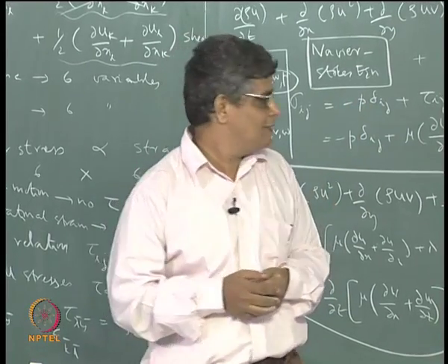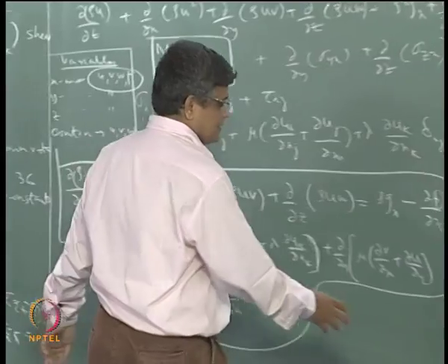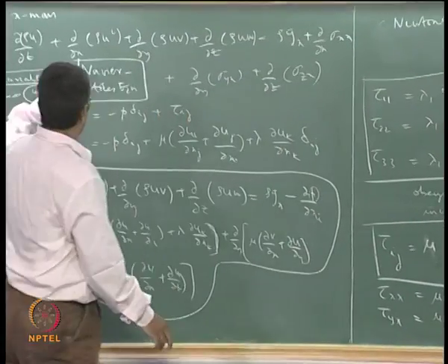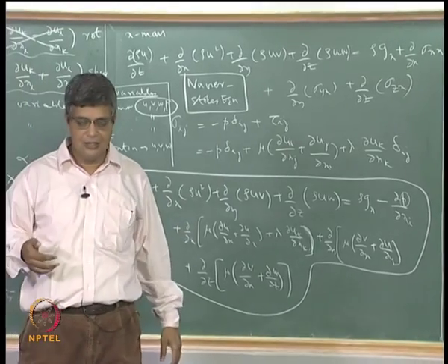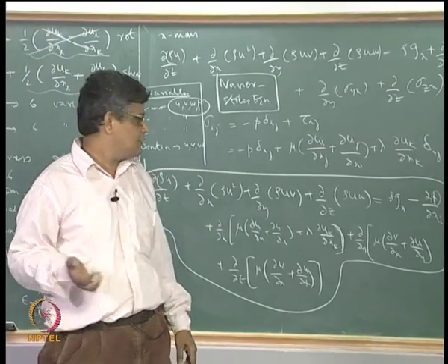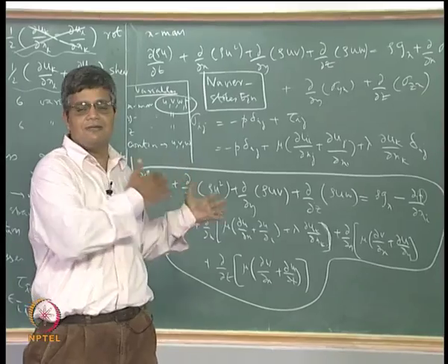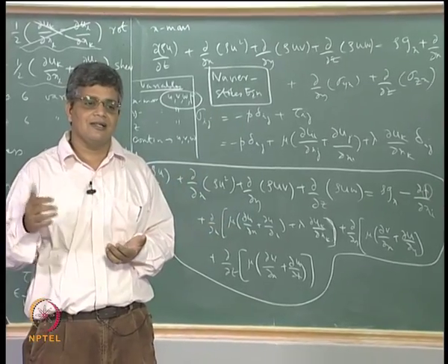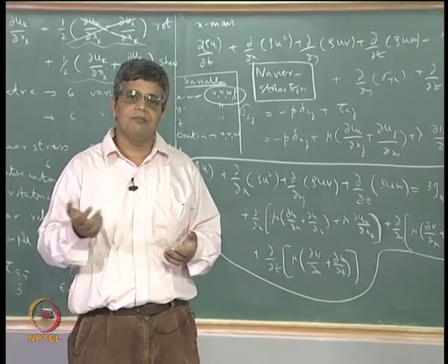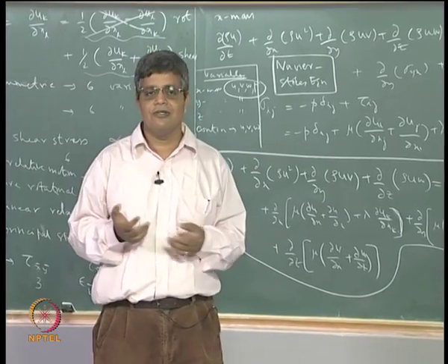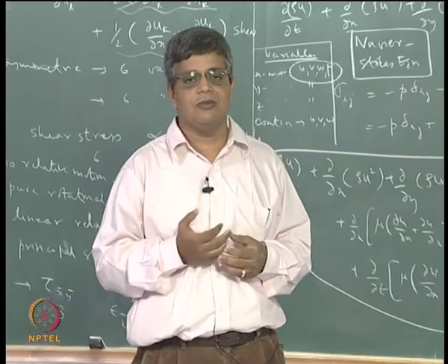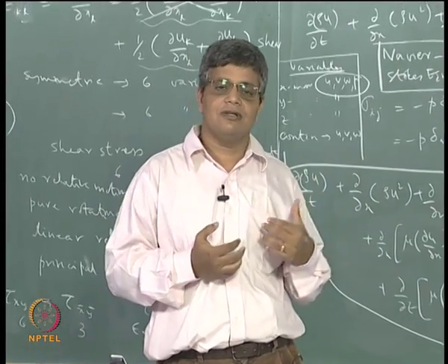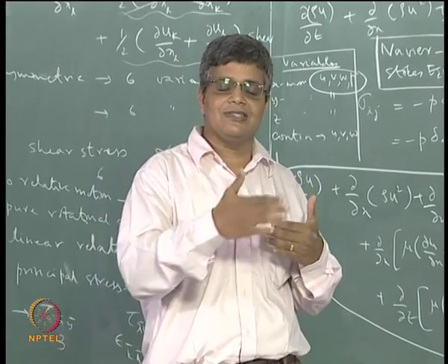So, for such fluids, this relation is no longer valid, and the Navier-Stokes equations are also not valid. You will have to have a different kind of constitutive relation which expresses the shear versus strain relation, and there are power law fluids, Bingham plastic models, and then dilatant fluids, and viscoelastic fluids which have even more complicated constitutive relations between the stress and strain rate.